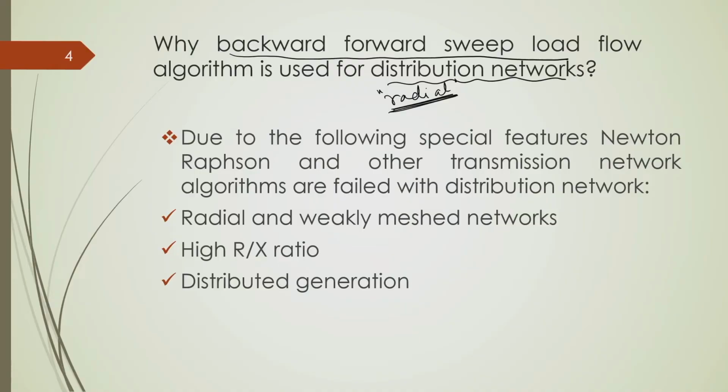For radial distribution networks, some of the conventional load flow approaches do not work, because they have some specific characteristics, particularly radiality, and the R by X ratio is usually high in power distribution networks.